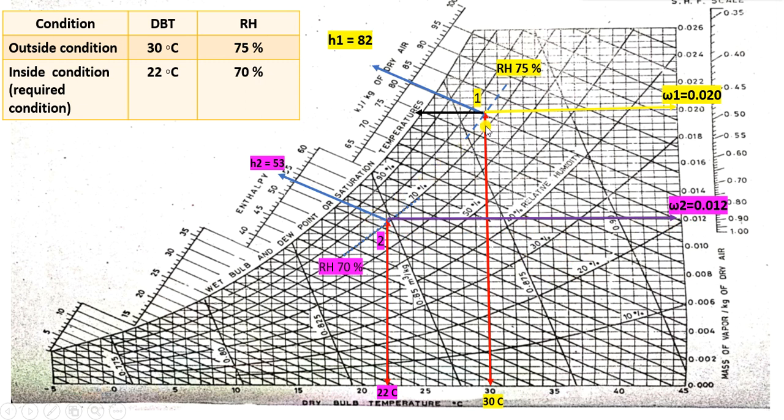Next, as mentioned in the question paper, first we need to do cooling, understood. Here this is the outdoor condition, and this is the indoor condition, that is the inside or required condition. Between 1 and 2 you have to draw. We cannot join point 1 to point 2 directly. If you join these 2 points, it will become a cooling and dehumidification process, that is a single process.